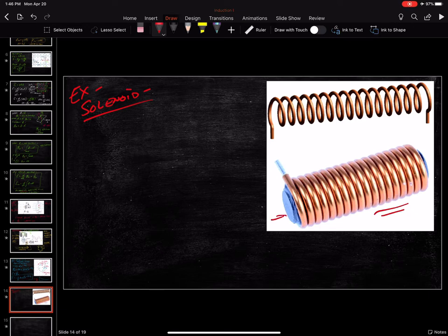This has just got an iron core, and you remember from our discussions of magnetic fields in materials, this means you've got this big magnetization inside here, where you get all those little magnetic dipoles pointing in the same direction, bumps up the magnetic field by thousands of times. Okay. So I want to figure out, well, what happens here? Is there going to be some sort of voltage induced in here? Okay?